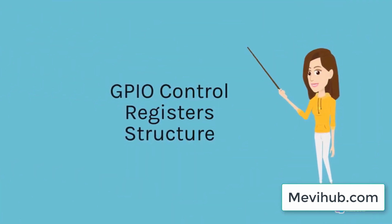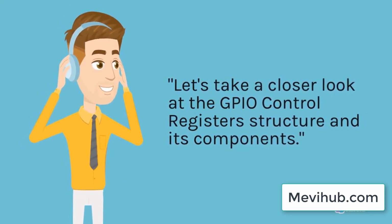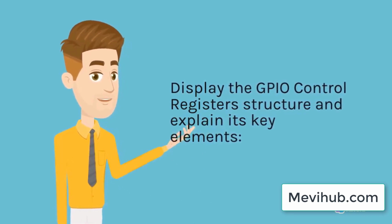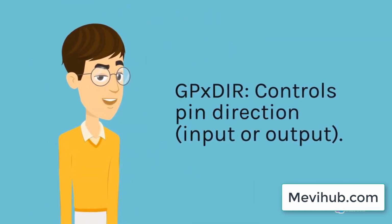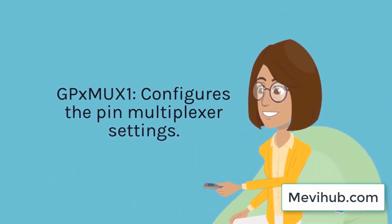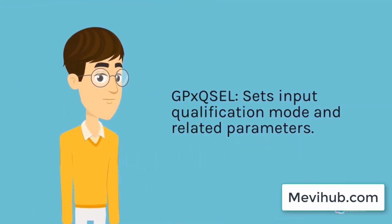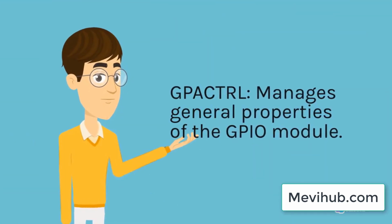GPIO control register structure. Let's take a closer look at the GPIO control register structure and its components. Display the GPIO control register structure and explain its key elements. GPDIR controls pin direction, input or output. GPAPUD enables or disables pull-up resistors. GPAMUX1 configures the pin multiplexer settings. GPAQSEL sets input qualification mode and related parameters. GPACTRL manages general properties of the GPIO module.